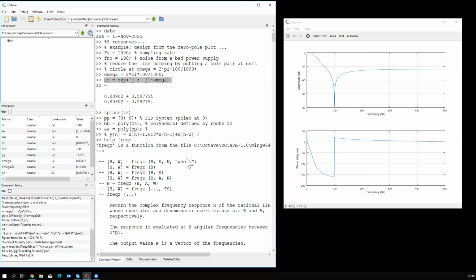Why complex conjugate pair? Well, otherwise, think of this product form compared to this sum form: how to get real values for system coefficients. You must have the special points either as complex conjugate pairs, or if you have a single one, then it must be on this real axis. Same way as in analog systems, complex conjugate pairs.